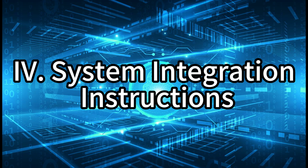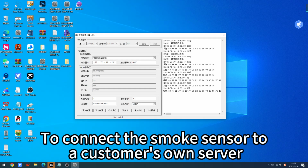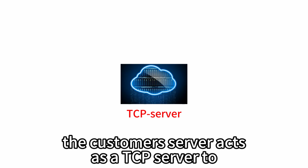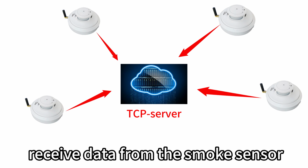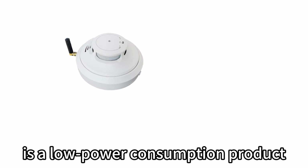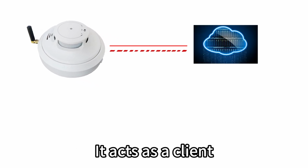4. System integration instructions. To connect the smoke sensor to a customer's own server, simply set the server's IP and port in the sensor. Once configured, the customer's server acts as a TCP server to receive data from the smoke sensor. It should be noted that the smoke sensor is a low power consumption product. It acts as a client.